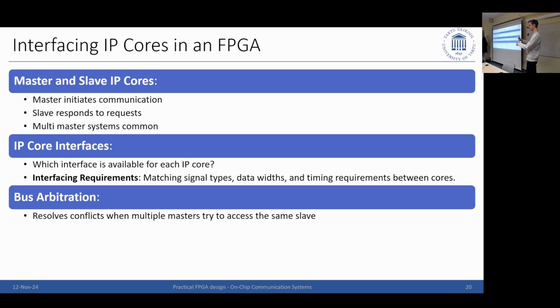But really gotta think, when you come to communication systems, you have to have your full system in mind. When you just do an IP core, maybe you just want to make it an AXI 4 standard, simple, so everyone can use it as they want. But if my IP core would never require a lot of data throughput and it just needs to be controlled because it does something magically on its own, and the other interface goes somewhere else into a sensor, then you might just want to use an AXI 4 Lite to reduce overhead on the IP core. Maybe you also want to provide different options for your customer. So you have a version of your IP core with AXI 4 Lite, AXI Master, and so on.